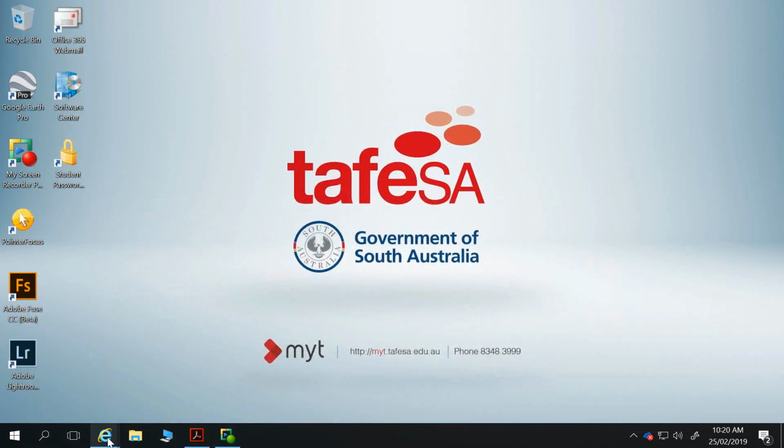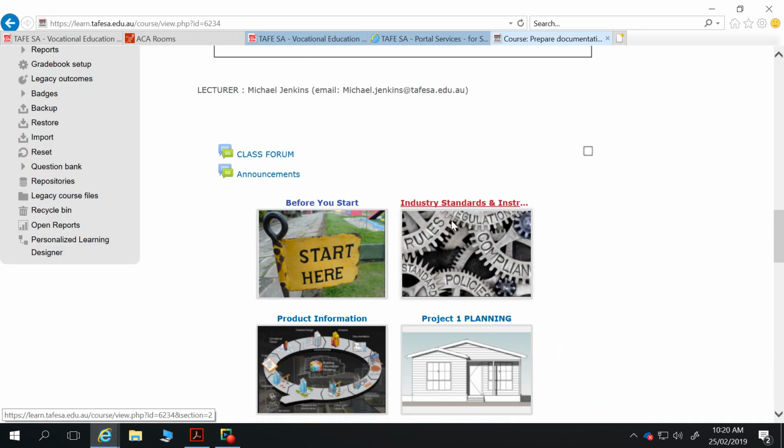I think it's a very important thing for us to understand as designers, the interplay between things such as solar access, thermal mass, and cross flow ventilation. Often you've got complementary or competing factors that you have to weigh up with a design, and you also have to balance that against other desires of your client, such as views and orientation on the site in terms of access and things like that.